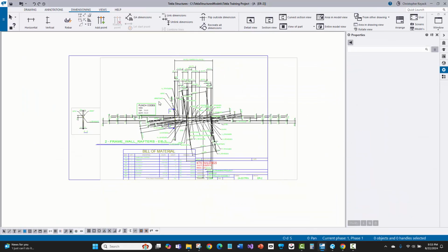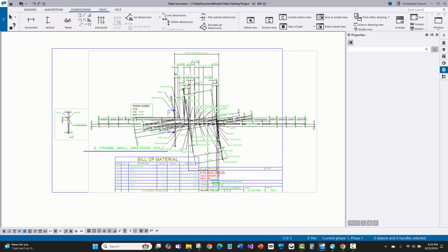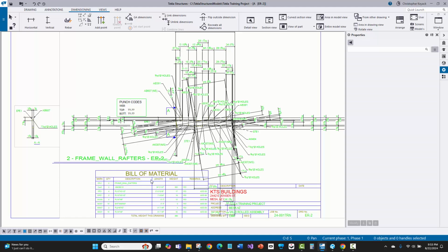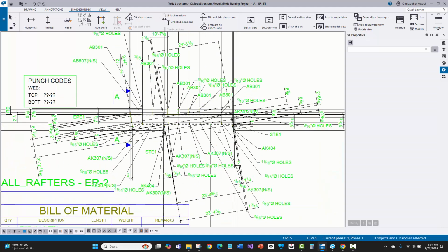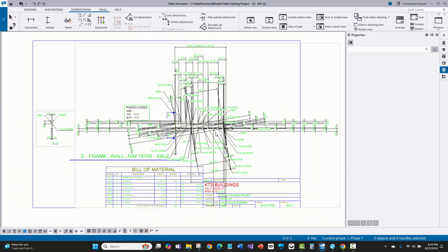So this is the kind of stuff that scares people. When you don't have my setup and good save settings as starting points, and you use out-of-the-box Tekla US settings that are designed for conventional steel, things get a little bit out of control. So for girts and purlins and jambs, things with no connection clips, especially skewed parts, the integrated dimensioning does really good. And that's why I have my cold rolled settings using those dimensioning styles. And this is a rafter though, so this isn't something simple, and it's got a bunch of skewed parts on it, and that's why this looks a little bit trashy, kind of a Chia Pet of lots of different stuff.